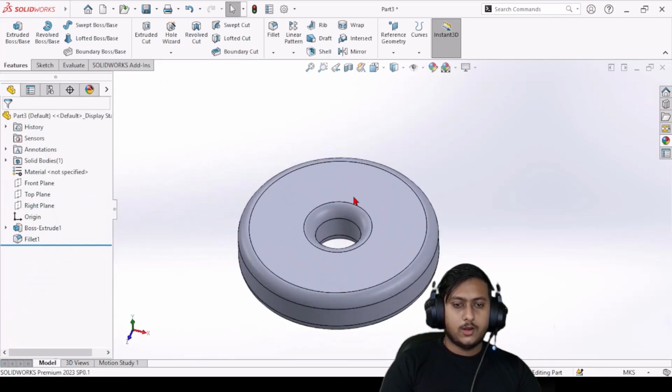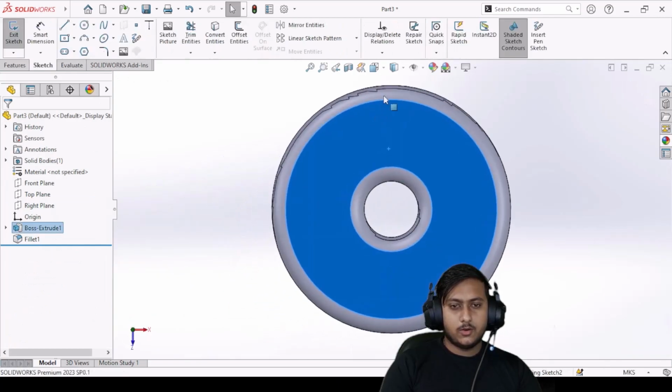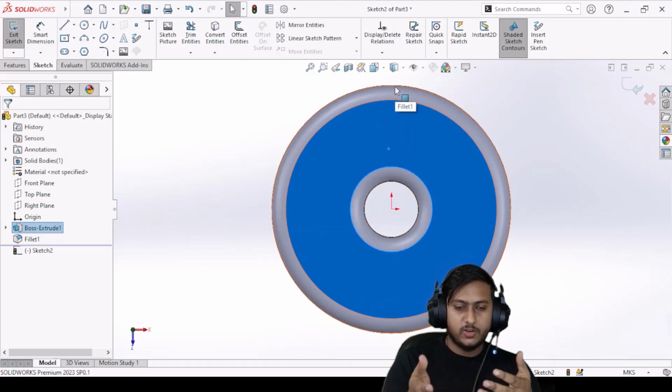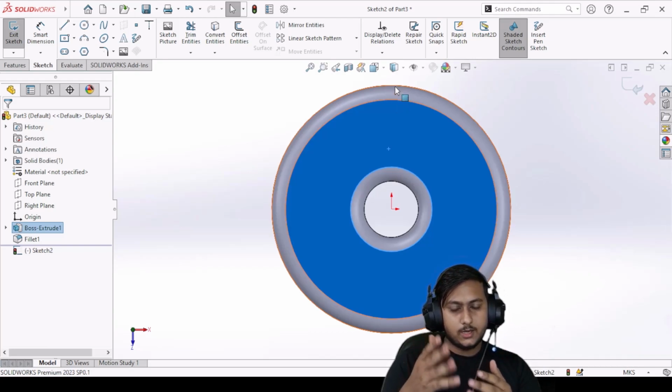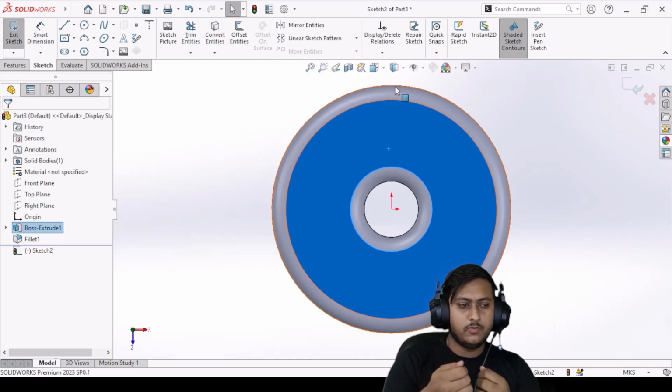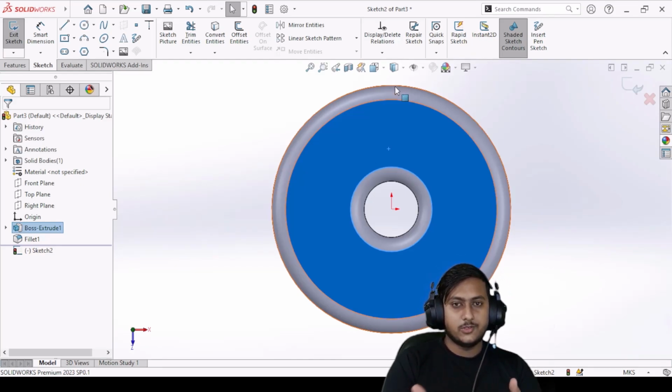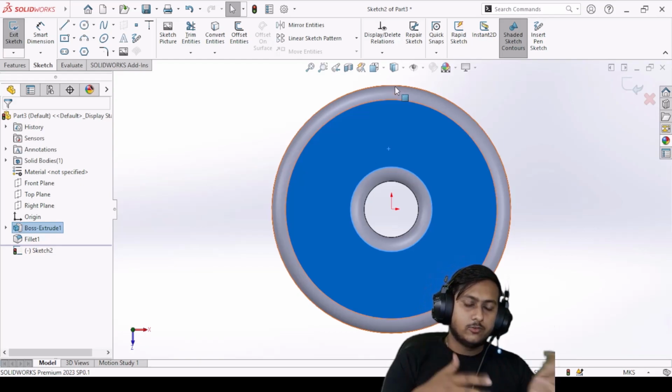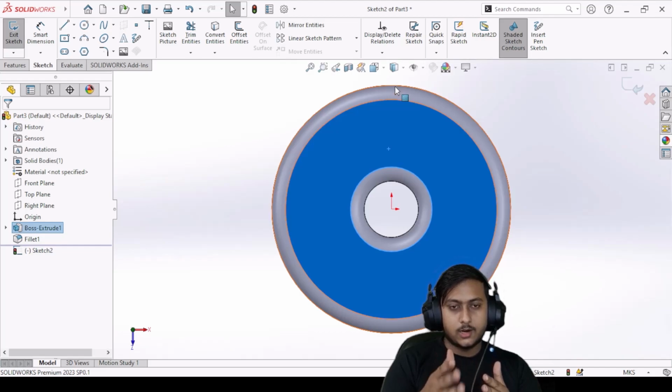Right, and just make a cut on the top portion of it a little bit for fitting this structure inside that valve, right? So we must need a cut, so it can be reshaped or fitted easily after manufacturing. In SolidWorks you can easily mate it by using circular mate feature and coincident mate feature. But for the actual manufacturing process, there is a cut between it, right?